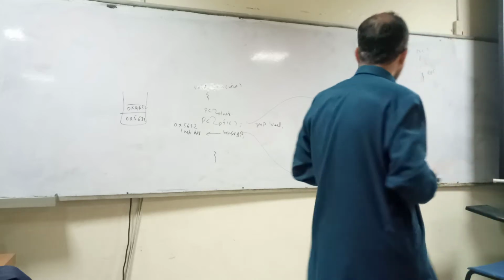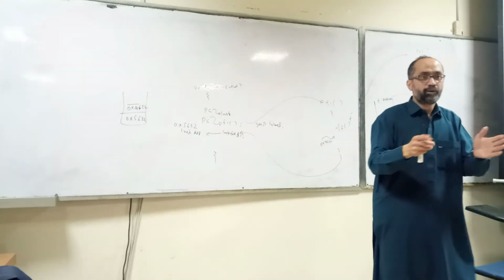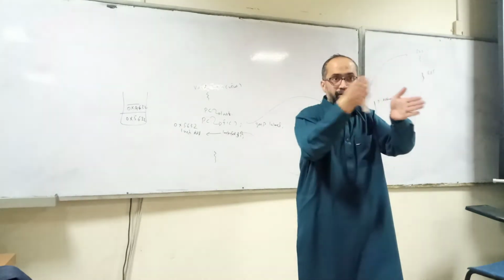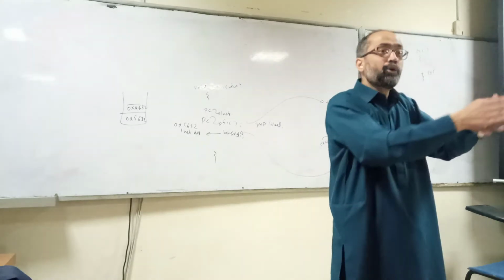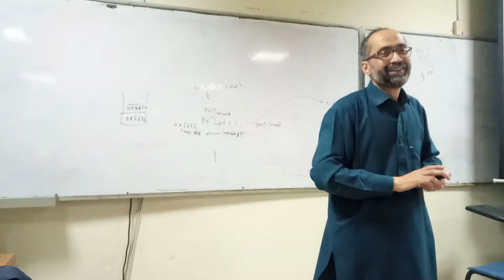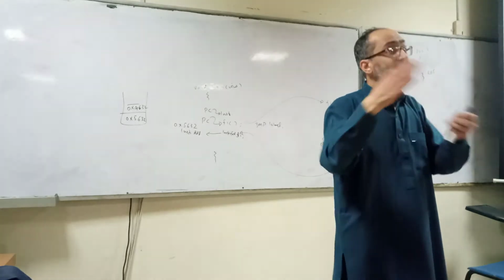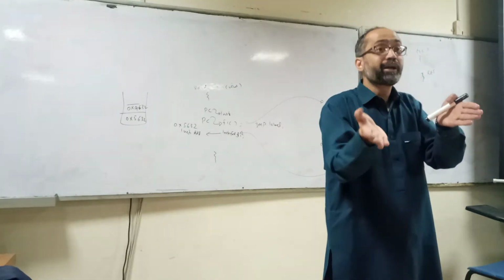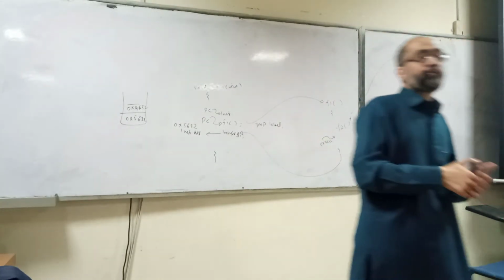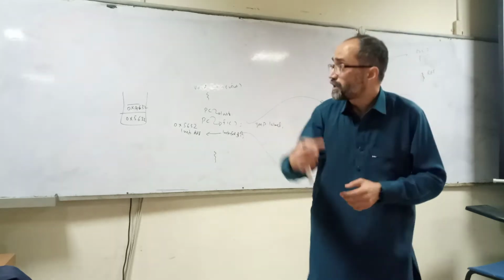So how does the microprocessor execute instructions? Typically, the microprocessor executes instructions in sequence. How is the flow changed? Through loops or through jump instructions. There are different types of jump instructions: conditional jump and unconditional jump. If you are calling a function, is it a conditional jump or an unconditional jump?